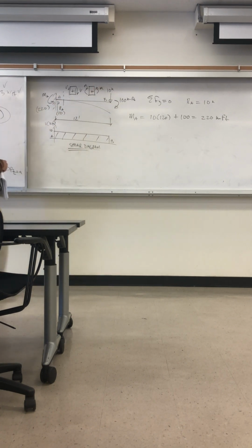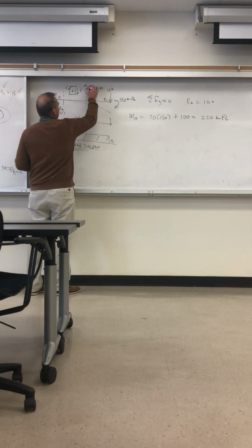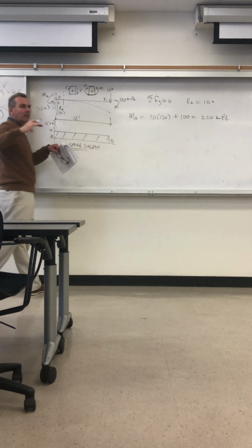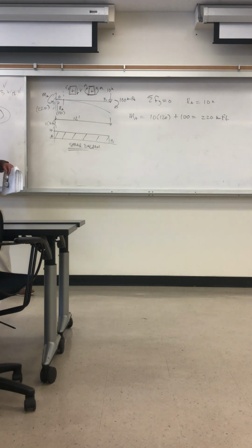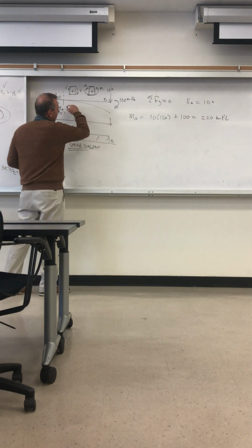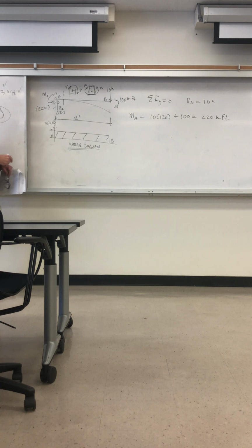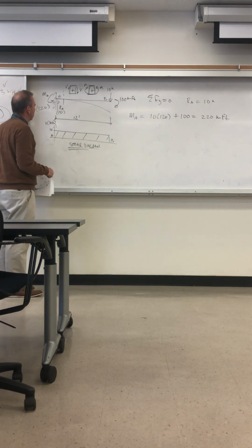It causes a curvature across the section like this, shortening the fibers above the neutral axis, extending them below. So that would be positive. This is negative, it's in the opposite direction. At all locations, the curvature is the opposite to that. So just visually, based on my approximate deflected shape, greatly exaggerated vertically, you can see that it must be negative curvature.